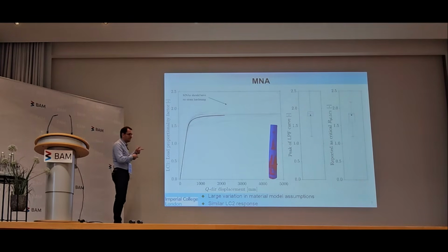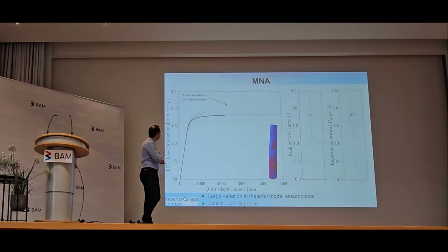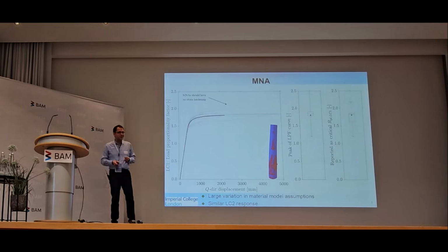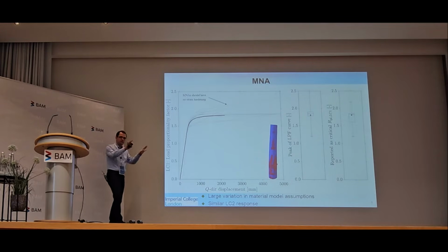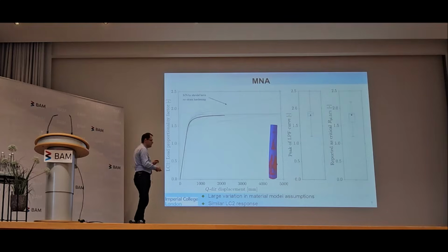So there is one sin associated with overestimating your MNA because of strain hardening. There is another sin associated with underestimating it. And so I did follow this up. Quite a few submissions basically killed the analysis once they began to get a little bit of yielding. They said, okay, it's beginning to yield, stop. I'm stopping, that's my MNA result. So that's one sin. Another thing that was reported was, oh, I'm getting a lot of yielding. My software is reporting 10% yield.